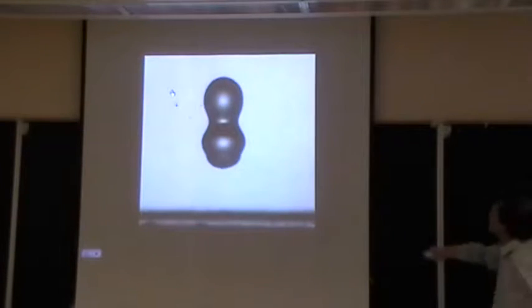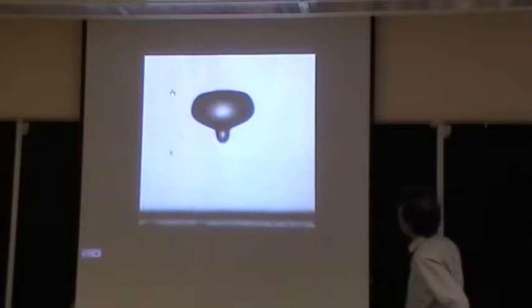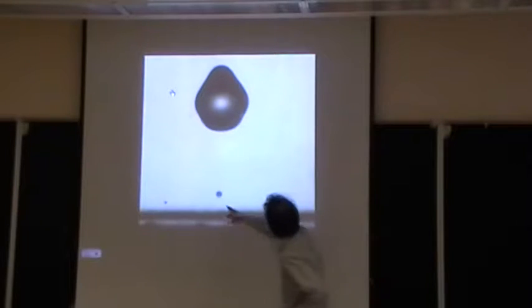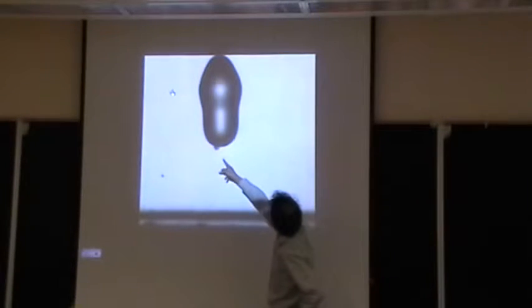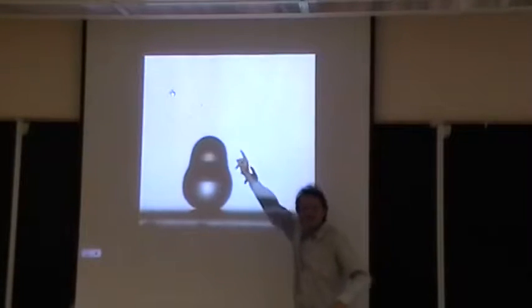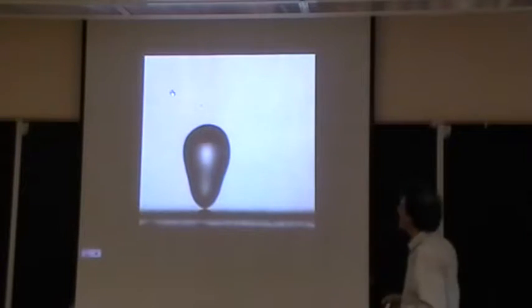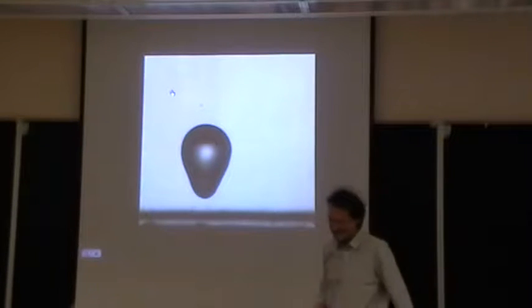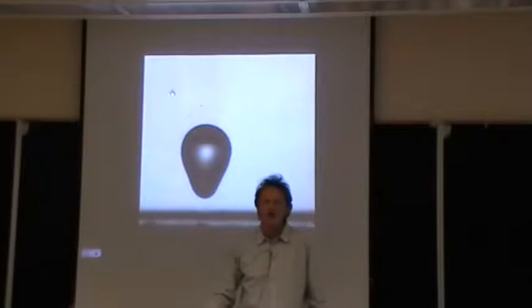This is just water, and so the succession of images is of course very nice. There was a very little satellite here, and the second one, which was emitted. Look at the coalescence between both. It makes a little daughter drop, which comes back to the solid. So you have the big one and the little one. Look at the little one. It hits as a solid ball, while the big one is very soft. This is a consequence of the Laplace pressure. You see, a bubble was ejected and a little jet, so it's a singular event. Singularities at interfaces are a very interesting theme, and so on. So it's something which is extremely rich. I hope someone could write a song.